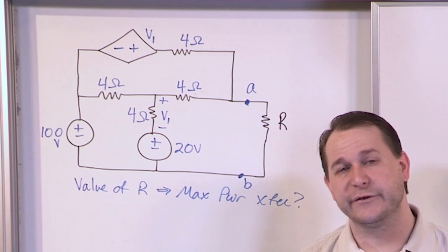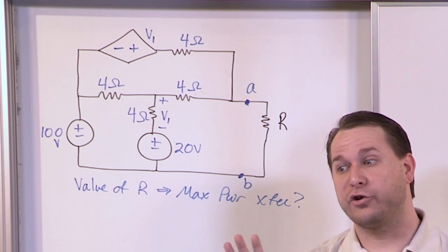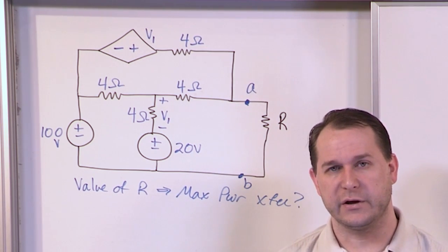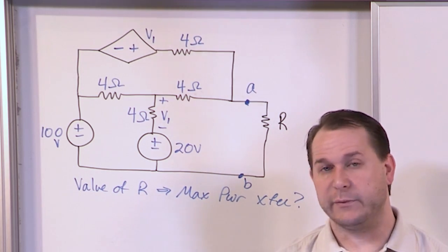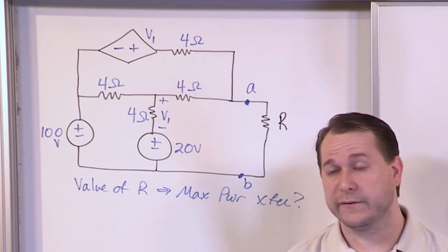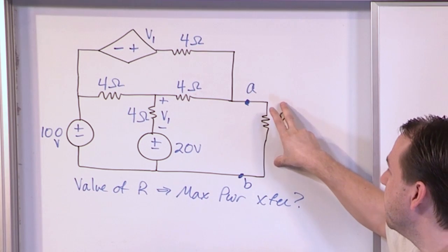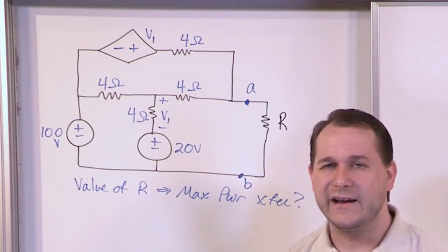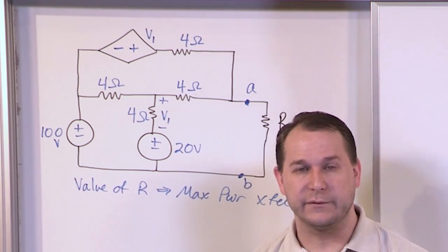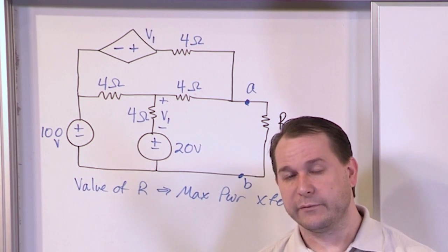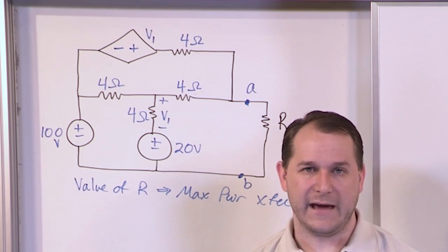And then we can calculate the voltage that falls across that current source that we hook up out there. And as we talked about before when we did these Thevenin equivalent problems, by getting the ratio of the voltage drop across a known test current, you're basically calculating the Thevenin resistance of the circuit as a whole as it behaves.